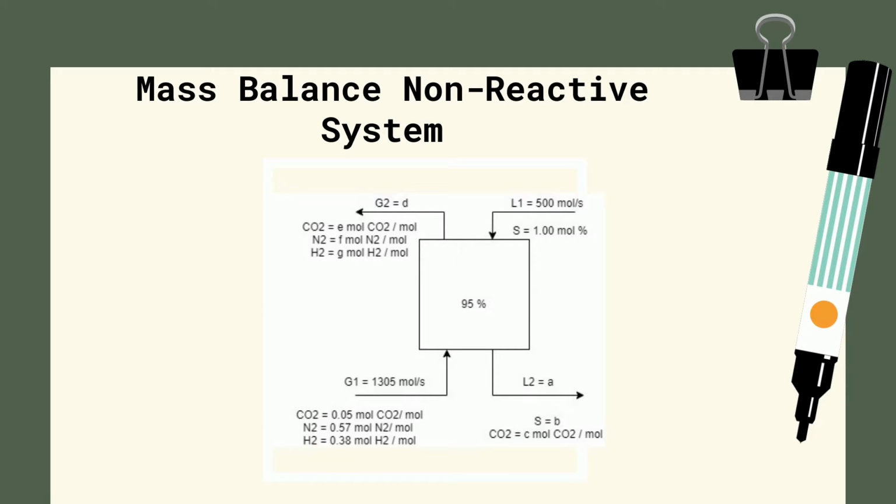To solve this mass balance part, the element balance method has been chosen. By using element balance such as CO2, N2 and H2, we managed to get their mole fractions. Thus, we could complete all the unknowns and proceed with the energy balance part.